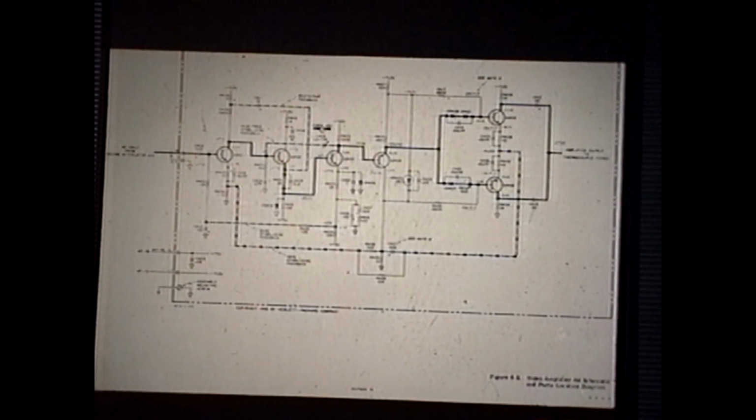1965, Hewlett-Packard. This is the input amplifier. Actually, not quite the input amplifier. It's the main video amplifier for a thermal RMS voltmeter, 3400A. So we got about 40 megahertz of bandwidth here, stacked up stages. This is an interesting amplifier to study because about every trick known to humanity to get flat bandwidth within 1% to 10 megahertz is available in this stage.